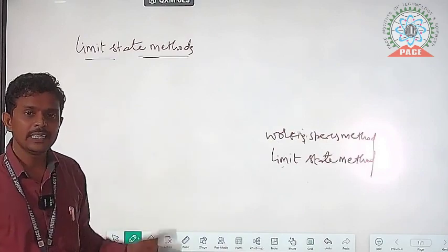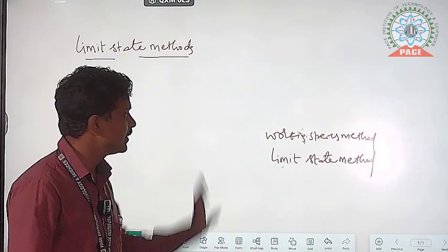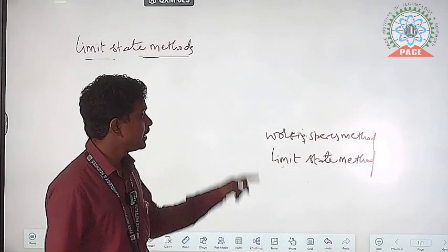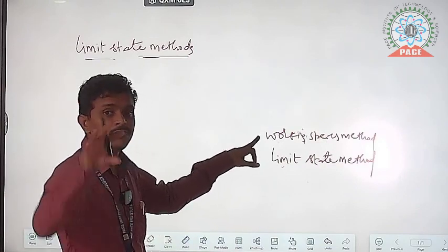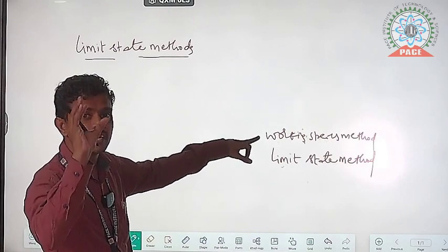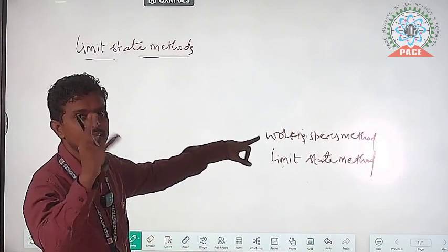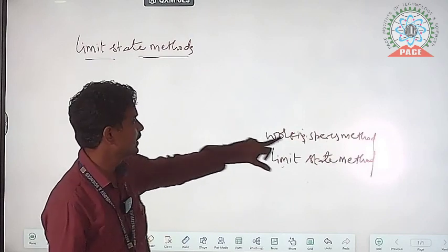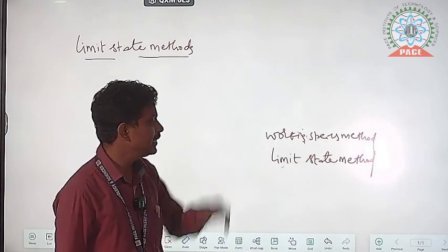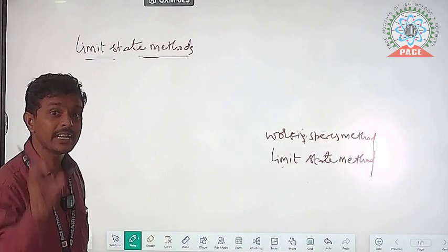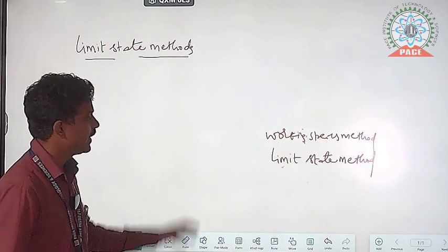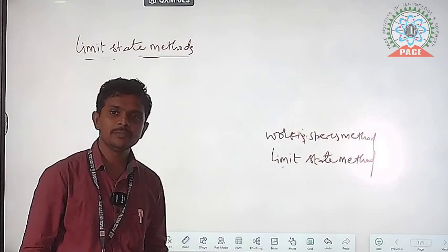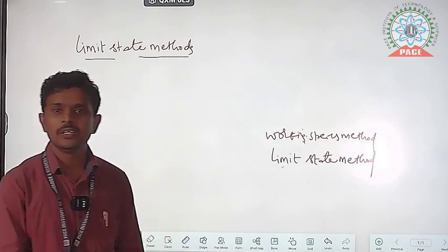But if we go for the working stress method, in future whatever problems come, the structure cannot resist them. Why? Because that resistance is not considered in the working stress method, but in the limit state method that factor is considered. We apply the factor of safety. Whatever problems come, the deflections, cracking, vibrations, all the problems we can solve by using the limit state method.